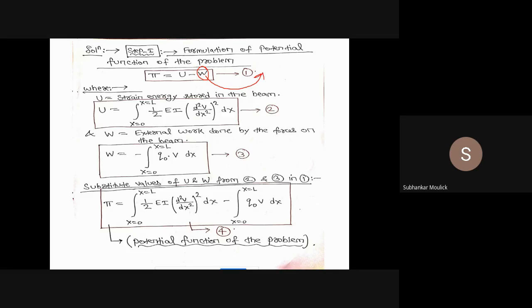First component is work done due to traction force, which is nothing but a UDL, because we call UDL in FEM as a traction force. The second component of this external work done is the body force, which is nothing but the self weight of the beam or the bar, and the third component of W is the work done due to point load, that is force into displacement U.